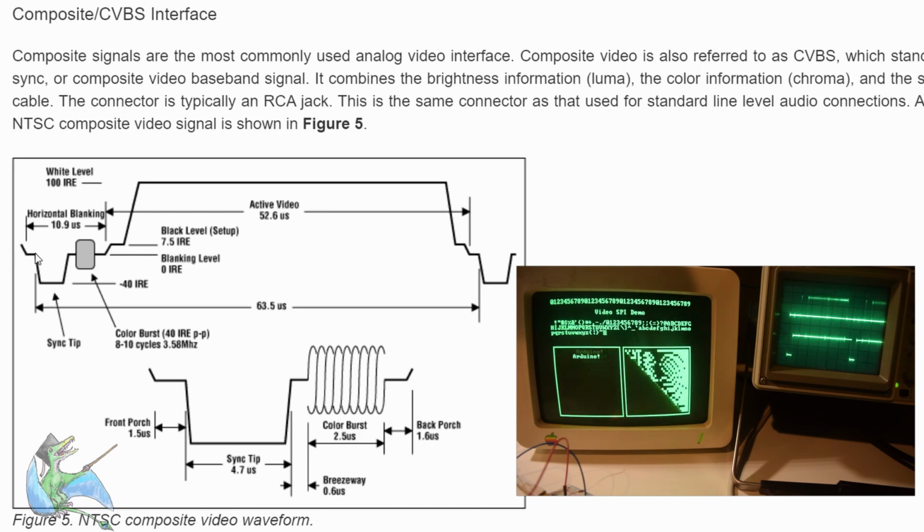That is where there's a baseline black level, which you have because remember, there's just a single signal wire in composite video. There's a baseline black level, which is not 0 volts. It's actually roughly a third of the way between 0 volts and the top voltage that's supposed to come out of it, which is like 1.3 volts or something like that.